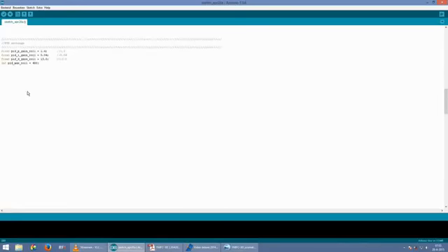At the top of the program, the PID gain settings are adjustable. Because we don't want the controller to go completely crazy, we limit the maximum output. In this case, the maximum output is plus or minus 400.